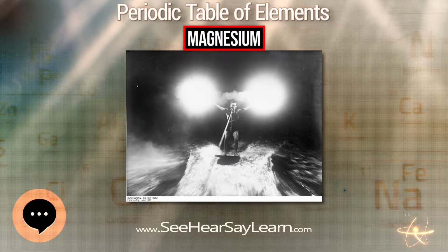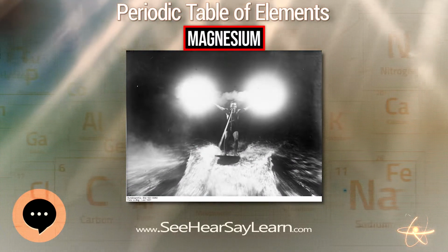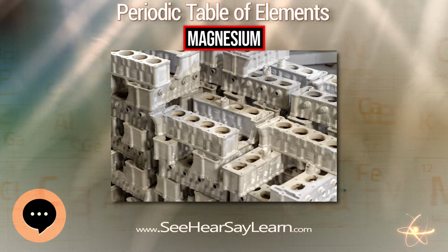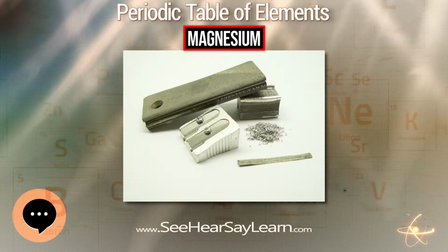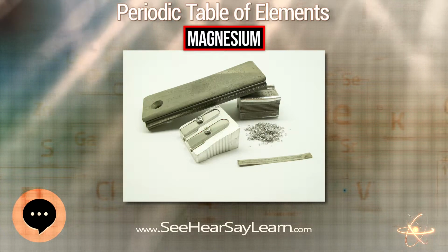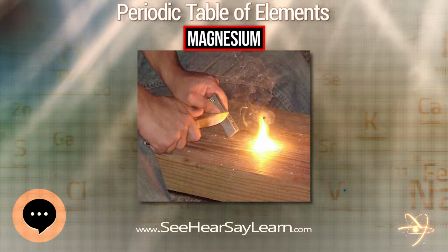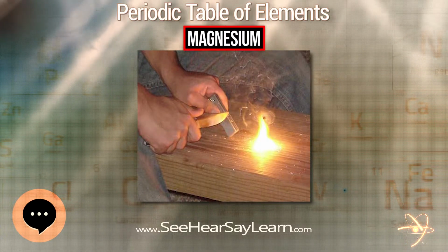China is the dominant supplier of magnesium, with approximately 80% of the world market share. China is almost completely reliant on the silicothermic Pidgeon process to obtain the metal. The process can also be carried out with carbon at approximately 2300 degrees C.